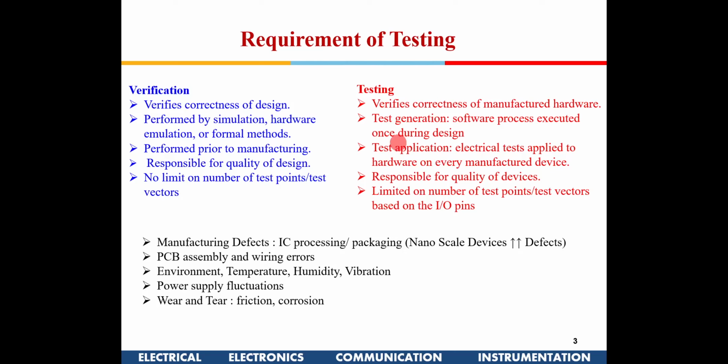So during testing we are not checking the functionality of the chip. The functionality of the chip is ascertained during verification, and during verification we also do process variation, temperature variation and things like that. So all those things are already taken care of there.